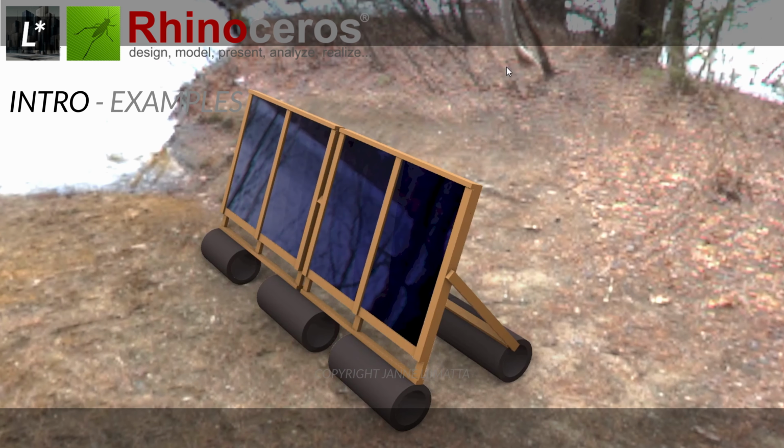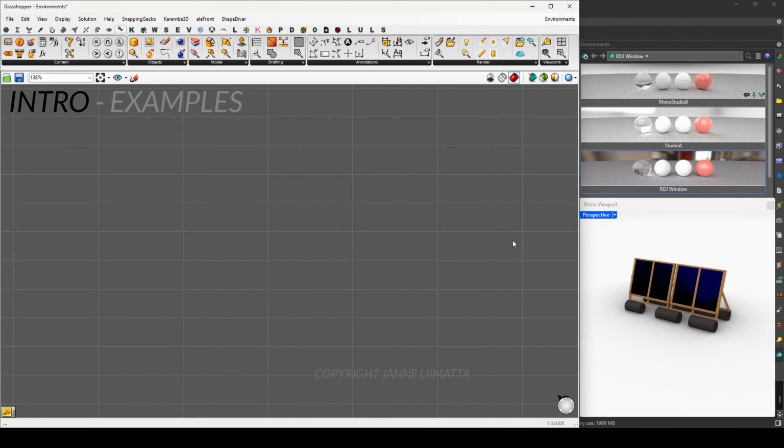Hello, after watching this video, you will know how you can import Rhino environments and query them from the Rhino model to Grasshopper for further processing. We'll be using the Import Model Environment and Query Model Environments components, which you can find in the Rhino tab's Render section.